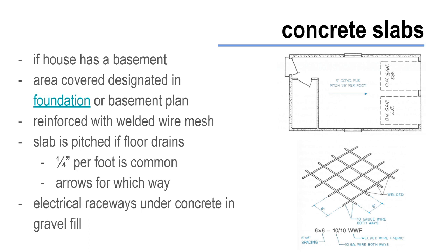An oversized raceway in that concrete slab may cause it to crack and settle unevenly. So you need an electrician to be there during concrete placement to help make sure that there is no damage happening to any of the electrical raceways.